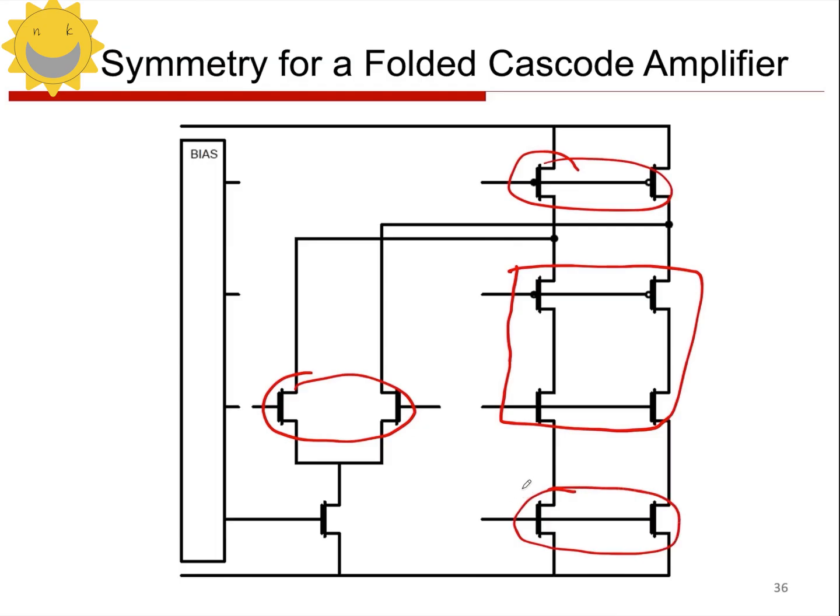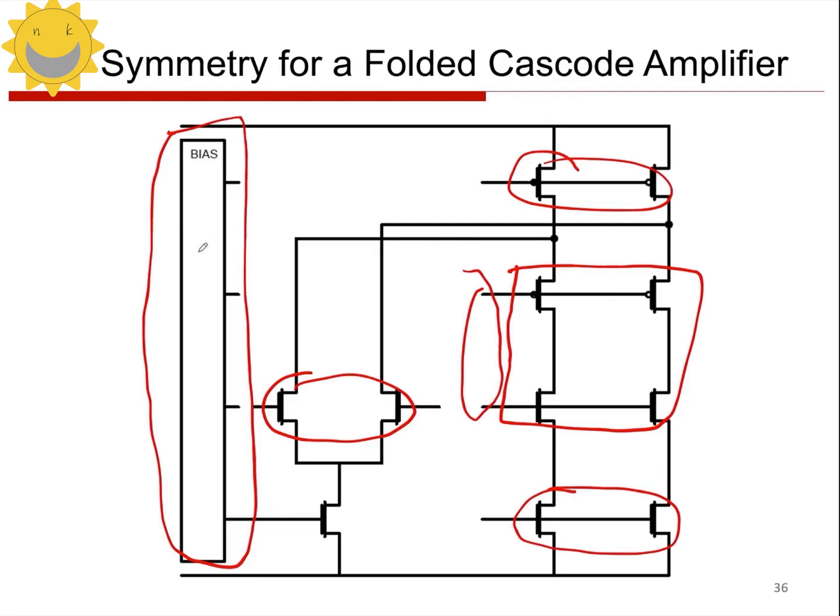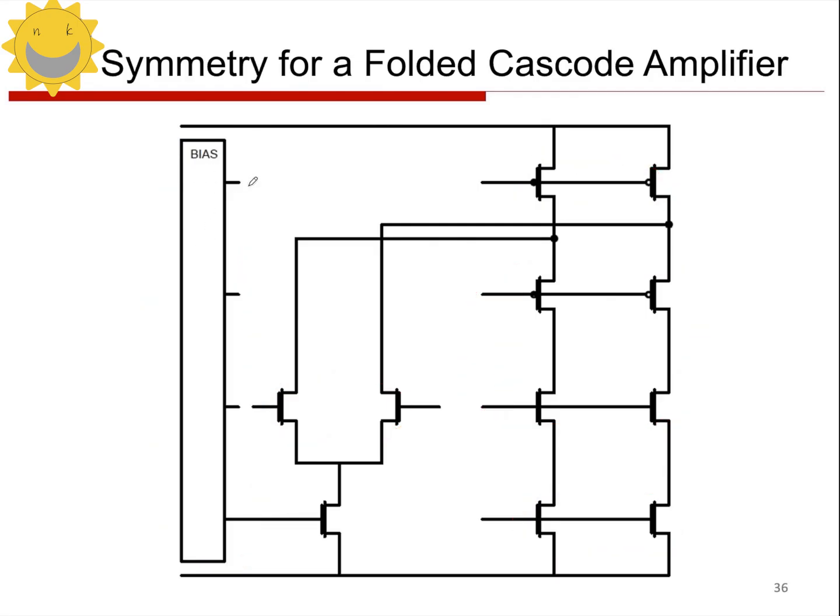What we just discussed is the main part of the operational amplifier. Besides this main part, what else is there? It's the biasing of the operational amplifier, right? The biasing circuit is responsible for providing the current mirror, whether it's for mirroring the current or supplying the bias voltage. Now let's take a look at how we can lay out and draw the schematic for such an operational amplifier.